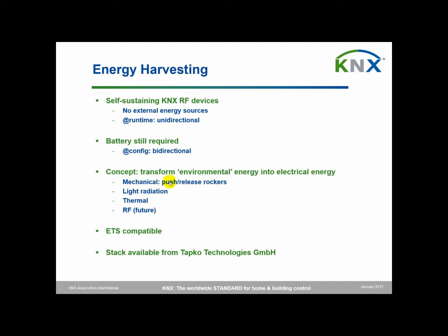So what is the concept of an energy harvesting device? Well, that is to transform environmental energy into electrical energy. That can be done mechanically, through the energy used by the user who manipulates the rockers of a push button. Because of pushing and releasing rockers, some mechanical energy is transformed into electrical energy. Light radiation could also be an option.